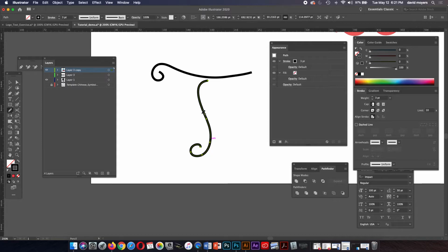Okay, now, what we're going to do to make this letter look cool is we're going to go in with the width tool. Some of you may have used this in our last class. Shift W is our keyboard shortcut. And I'm going to first go up here to this open path here, and I'm going to tighten it up so it goes down to a point. Then I'm going to come down somewhere in the path here and widen that out.